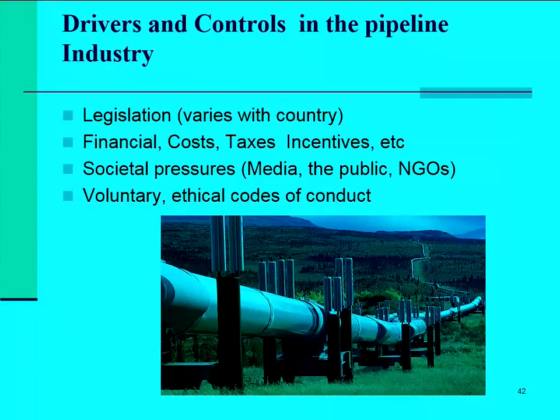Here you get an environmental permit from the Environment Agency, and it will say these are your limits on discharges to air, this is what you can and cannot discharge to sewer, this is what you can and cannot discharge to a controlled water, i.e. a river, this is how you should manage your waste, this is what we consider to be the best available technique for how you carry out your process. This is all to do with an environmental permit.